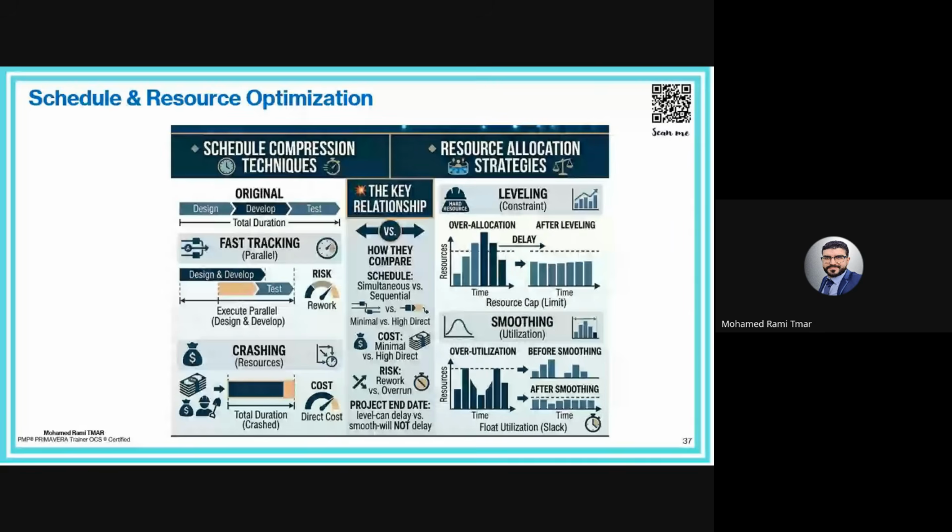Resource leveling is different. Resource leveling adjusts activities even if it impacts the schedule. Yani, we don't care if this activity has float or not. The project duration may increase. With a limited number of crews, we delay some activities. Sometimes we don't have any choice, especially if the over allocation is detected in a critical activity.